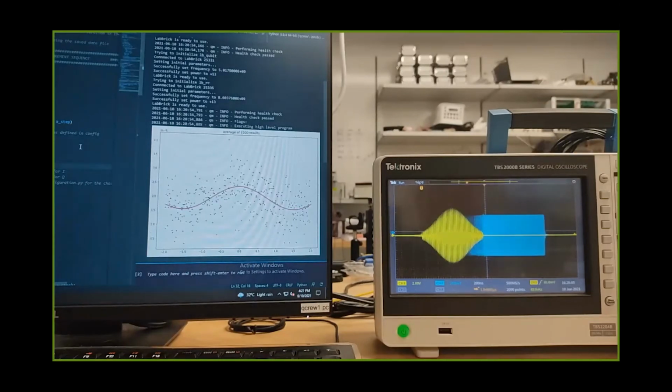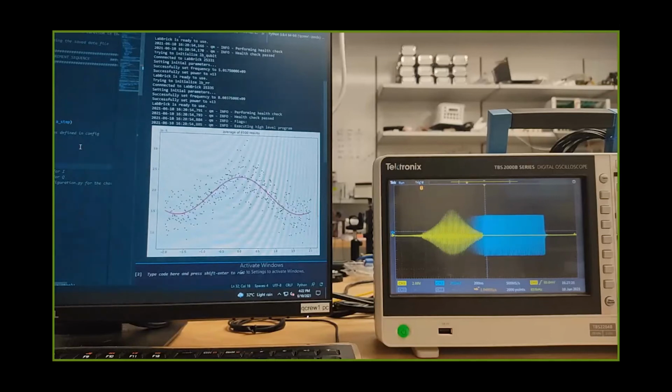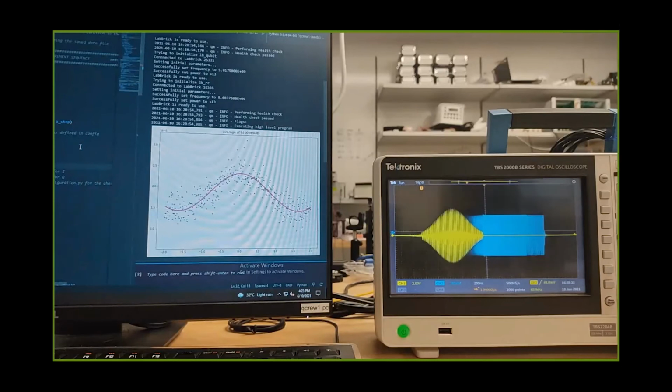This is our experimental setup. The oscilloscope on the right shows the drive pulse in yellow and the readout pulse next to it in blue. The reflected signal from the readout pulse is sampled and averaged over many repetitions for each frequency. The graph shown on the monitor has the same axis as the previous graph shown on the whiteboard, readout voltage against drive power. A curve of best fit for the points is seen to be slowly taking shape after more and more points are being plotted.